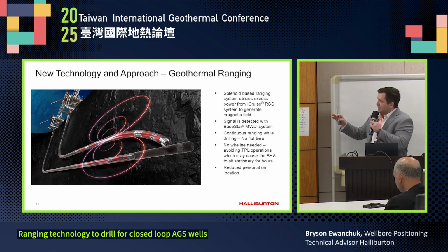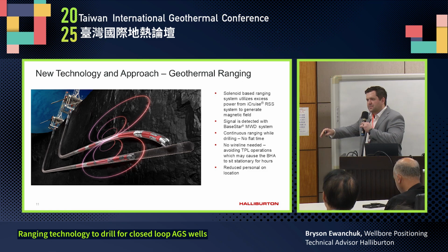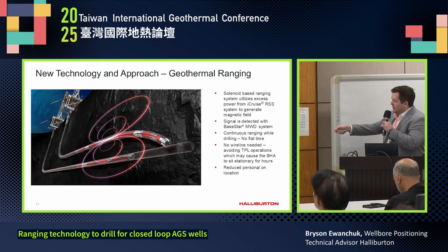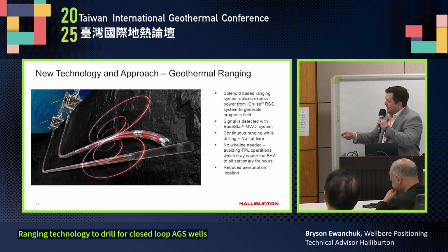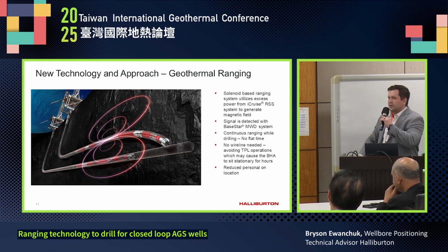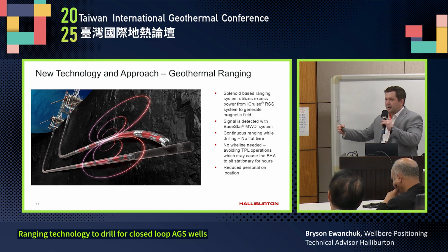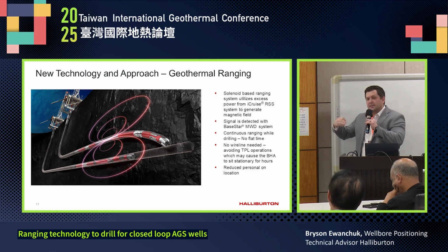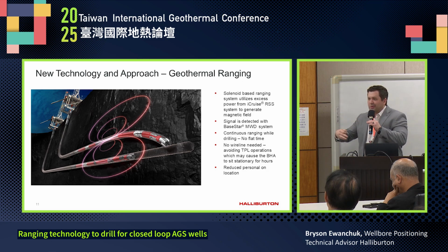The basic concept is that we have two drilling rigs drilling at the same time. In one rig, we have a brand new tool, which is called the excitation collar. The excitation collar gets connected to the iCruise rotary steerable system. In the top well there, long story short, the iCruise generates a lot of power. This collar also has internal turbines, so as we pump fluid down, it charges up. And it's a solenoid-based collar, which actually generates a large magnetic field.